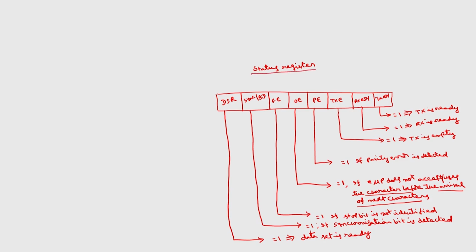So, the microprocessor can read the status register, thereby it knows the status of various signals. There are two other registers, the mode word register and the command word register. The microprocessor has to write something into those to set some specifications, whereas the status register the microprocessor reads. Okay. So, this is about the first block, which is the read write control logic block.